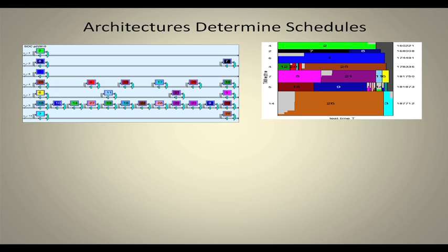Now, this 22810 has some 26 cores in it. In this case, the TAM is divided into a number of sub TAMs. The first one is of width 4, second one is of width 2, third one 6, then 4, then 7, then 5, then 14. Then the individual cores are put onto the TAM like this. On the first TAM we have only core 2, on the second TAM we have core 8 and core 7, on the third TAM we have core 1, and on the fourth TAM there are 25, 4, 19, 17, 20, 12, etc.